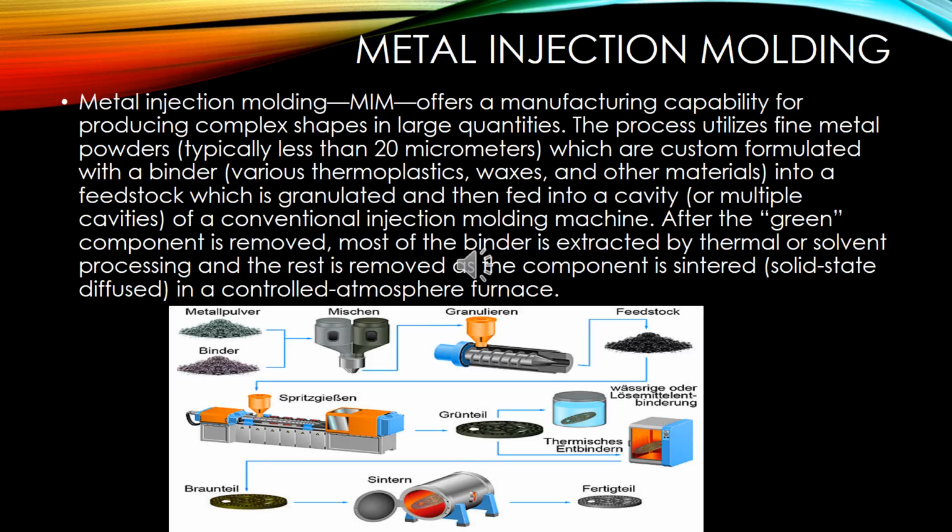Due to current equipment limitations, products must be molded using quantities of 100 grams or less per shot into the mold. This shot can be distributed into multiple cavities, making metal injection molding most cost effective for small, intricate, high volume products which would otherwise be expensive to produce.